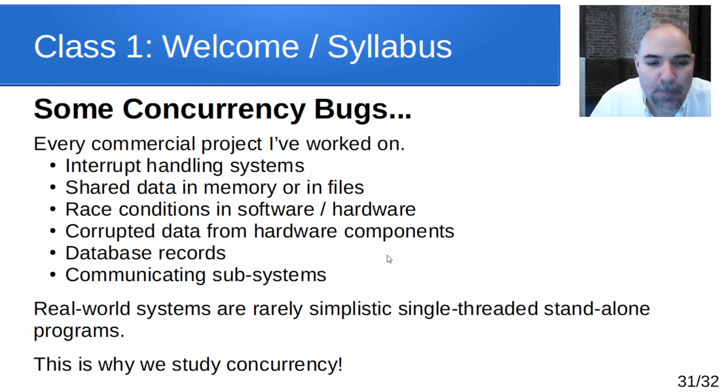I've had that happen. We're using a sensor like a gyroscope, and let's say it's a 16-bit output on the gyroscope, meaning it has 2 bytes. You have to read the first byte and then read the second byte. Well, when you're reading those, what happens if the value changes after you read the first one, but before you've read the second one? You'll have half of one reading and half of the other reading. And now you'll have a value that doesn't make any sense. It's corrupted because you've split that in half. So those kinds of things can happen.